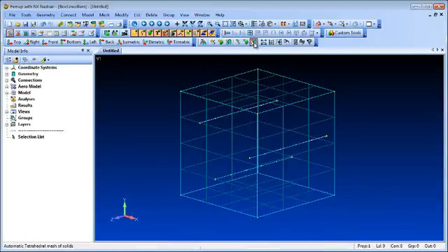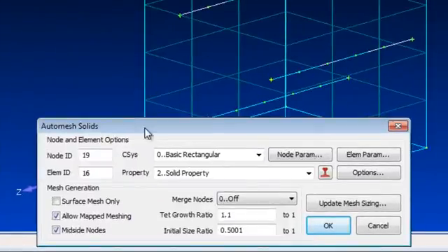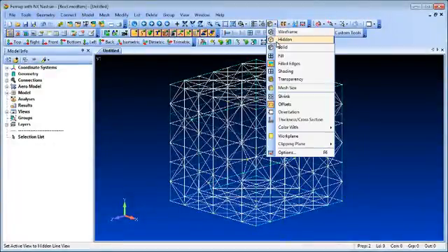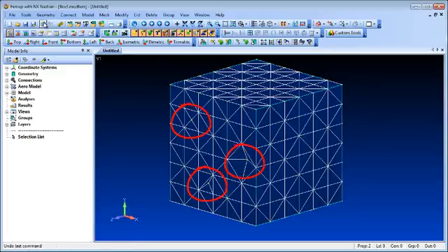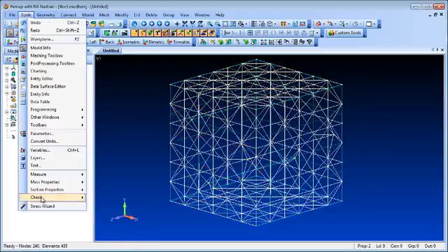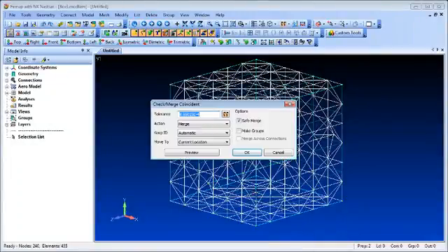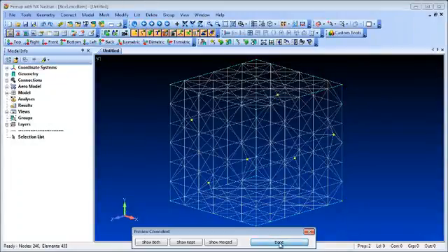The next step is to mesh the bounding surfaces, and we can do that by selecting the Solid Mesh command, electing to surface mesh only. Selecting a hidden line view at this point will show that the meshing points have been picked up correctly. Now, with the curves and surfaces meshed in separate commands, there will be coincident nodes at the mesh points that will have to be removed.